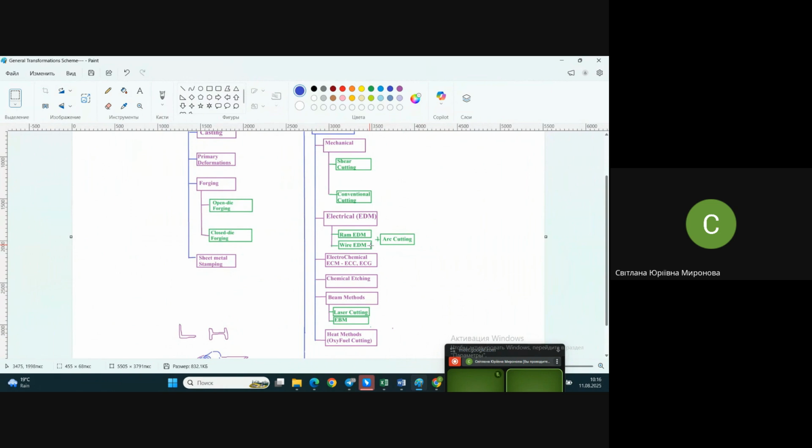If you exceed the temperature of so-called collective recrystallization, which is in a range of 0.5 to 0.7 of the melting temperature for different metals, you initiate a change of inner structure in superficial layers. And laser cutting will be worse in this sense. It's faster than wire EDM, but it leaves you a more spoiled layer on the surface.